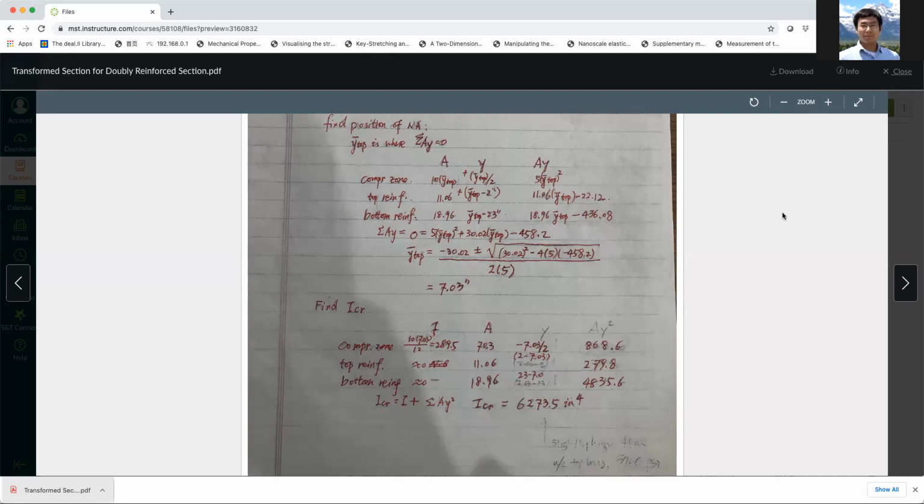All right. And I can see from my experience that we have a pretty good understanding of shear. One critical issue still relies on the differences between the total web width and the effective web width bw. As I said again, the effective width for the web is the least, smallest, narrowest distance across the cross section. So that is the common mistake I see over there.